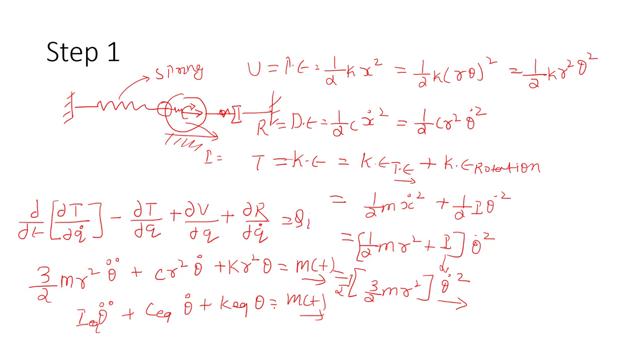Even though in this video my intention was not to go into so much detail, suppose someone asks you what is the natural frequency and the damping factor of this system. The quick answer is that omega n is equal to root of K equivalent by M equivalent.